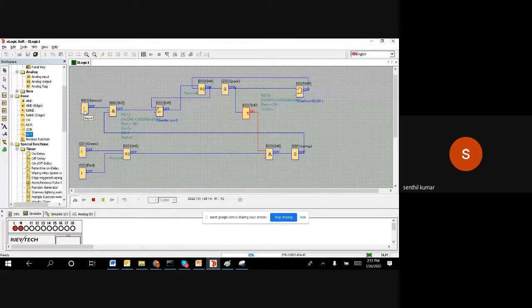But even if the sensor is giving, we don't want to trigger any action because that will paralyze the system. When everything is stopped and somebody is cleaning the sensor, it would start the packing motor by itself. We don't want that abnormal condition. So we have to make sure the logic we make is perfect, with no loophole, and works correctly. That's what it is.